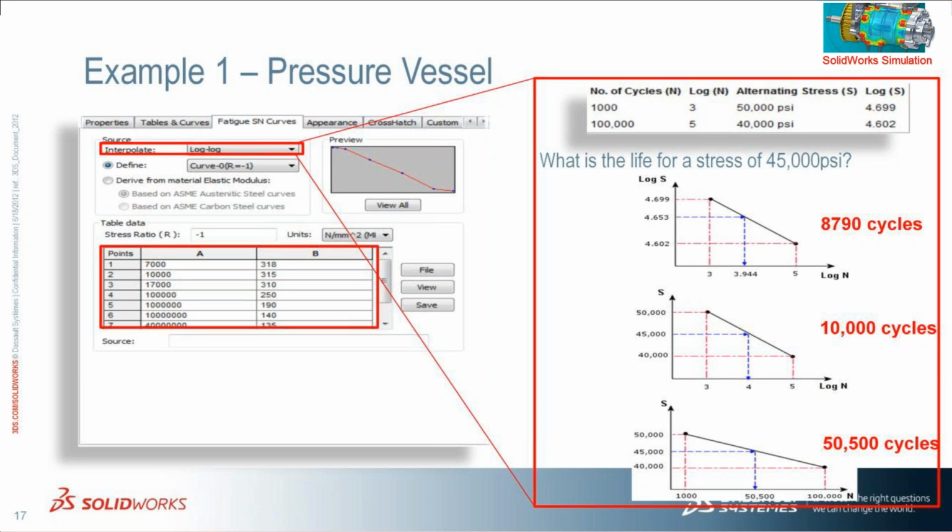Another thing, in fatigue analysis we can have a damage plot and a life plot also. That will be very helpful in predicting. You can observe here the stress ratio R is -1, as I said, fully reversed, and we can include this ratio here. This is the number of cycles, and this will be the stress results. After 7,000 cycles, what will the stress results be in that material?